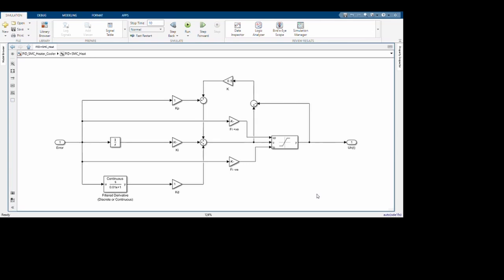We are applying limits to the input error. When we are simply multiplying this input error by 250, no matter what happens, eventually that error is going to reduce, and as soon as that error gets to 0, even if you multiply it with 250, the limits are going to be so small that the output is going to be clamped, and this clamping action is exactly what gives us our sliding surface.